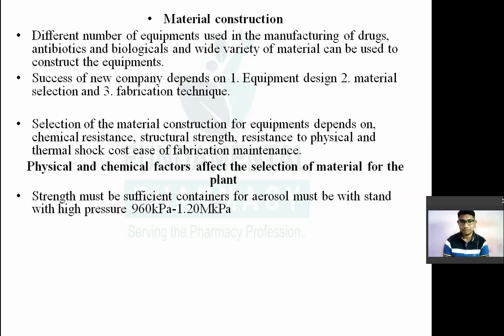No, it will not be plastic because your aerosol formulation is a pressurized formulation, and whatever container you are using must withstand high pressure up to 960 kilopascal to 1.2 megapascal. So that should withstand the high pressure. That is, your material should have enough strength.